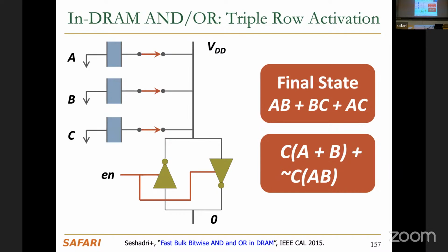A conventional row decoder can only activate 1 row. So the Ambit paper proposed to have a smaller row decoder that is able to activate 3 rows that are called the compute capable rows. And if you were using Ambit in such a system, you would be activating these rows a lot, right? And in that case, it might affect the nearby rows, right?